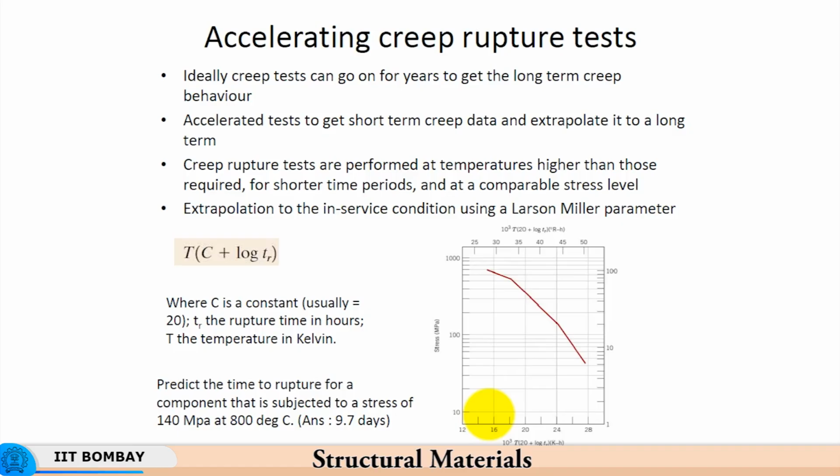Now, a boiler is an entity that can operate for years together, and so you do not expect any significant creep deformation to take place over even a number of years. So, if you have to test the material for creep and gauge its suitability for boiler application, you will invest one full lifetime before you can arrive at one single conclusion. That is the reason why people do accelerated creep tests to assess the suitability of the material for boiler or gas turbine or some such critical applications.